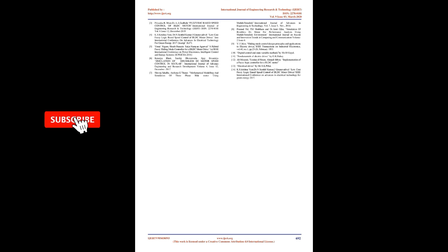3. On load with FUZZYSMC controller. For 900 RPM. FUZZYSMC 50%. Figures 9 and 10 show speed responses for 50% and 100% loading for the FUZZYSMC controller. It is observed that the FUZZYSMC controller is better than the sliding mode controller in terms of settling time, overshoot, undershoot etc. 8. Performance comparison of SMC and FUZZYSMC controller.